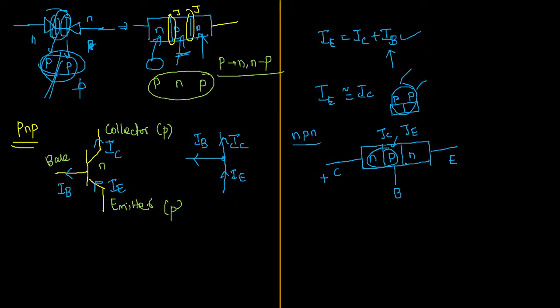Now suppose the collector junction is in forward bias and the emitter junction also is in forward bias, then what will happen? If both junctions are in forward bias, then the region of operation is called the saturation region. Just write it down. It is very important. Actually, we are entering a very important zone. I'm not covering the entire thing, as I already told you it's not the time to explore all the operations. I'm just covering only the things which are required to solve the problems.